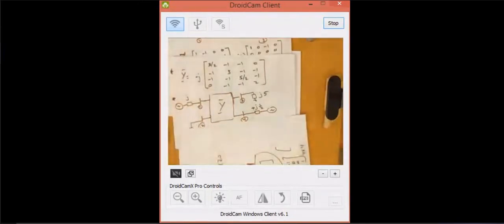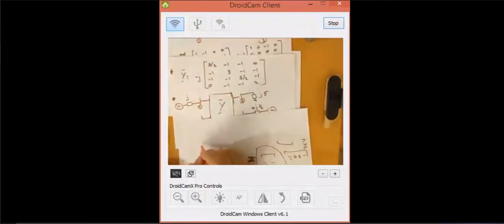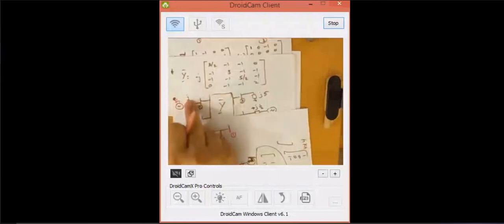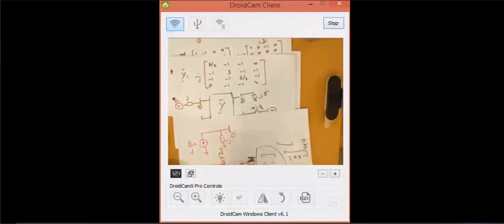Notice the generator. I can change it to a current source at bus number 1, in parallel with an impedance. The current source is E1 divided by j. And this is j, of course. j means that it is X, so we want to change it to Y, so it is equal to 1 over j, which is equal to minus j.